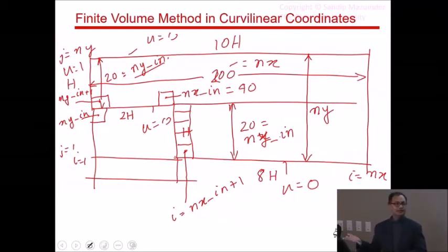This is again like a scalar advection diffusion equation problem you're solving. All right? So check that, check your V momentum equation also, and then check your pressure correction equation. Once you're satisfied with all three and you're sure that you can get them down to machine accuracy, then couple everything.